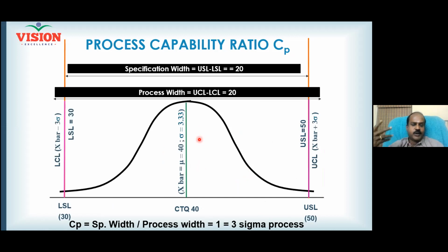Come on, make your predictions. Is this process capable? No, sir. Why not capable? It's a risk, sir. Both are overlapping, USL and UCL. Specification limit and control limit are overlapping. That means my process just made it, isn't it? It just made it, just capable.